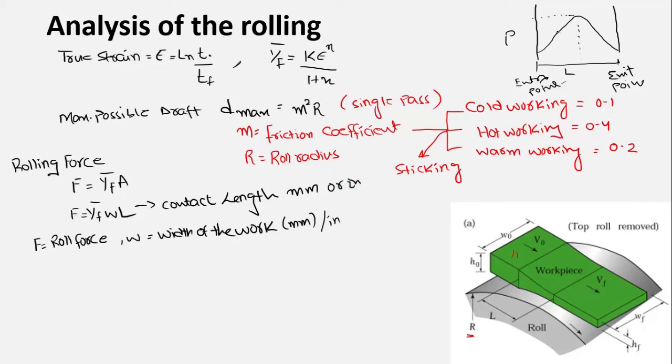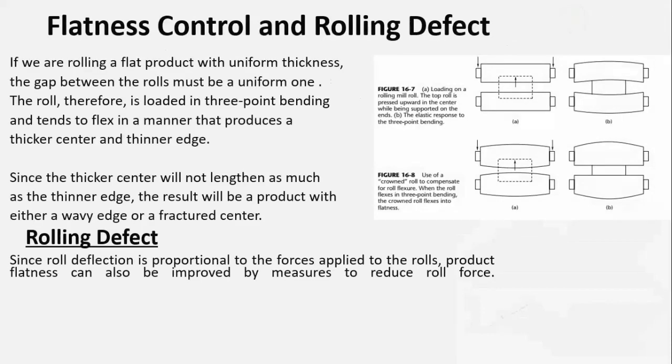Based on this we can say the force would be equal to the integral of p w dL, right? We know pressure is force per unit area, and stress is also force per unit area, so we can calculate based on the pressure as well, from length 0 to maximum length L, right? And it would be maximum at this point, so this force would be maximum at this point.